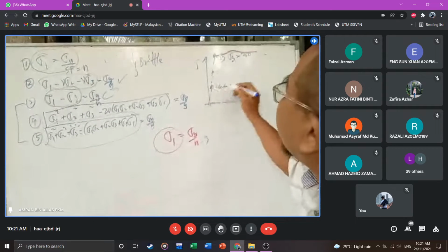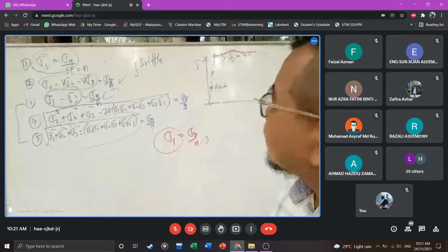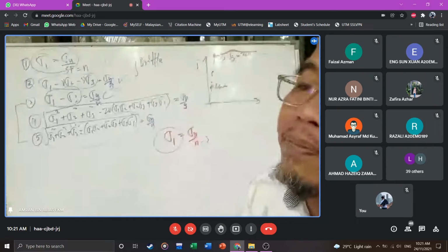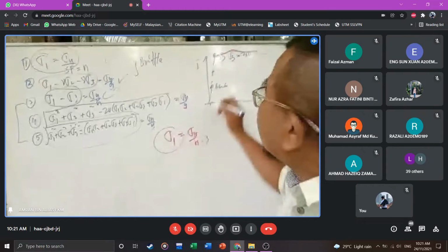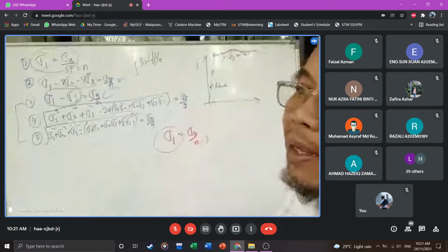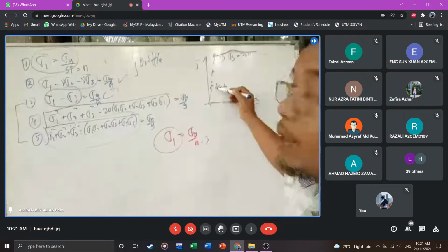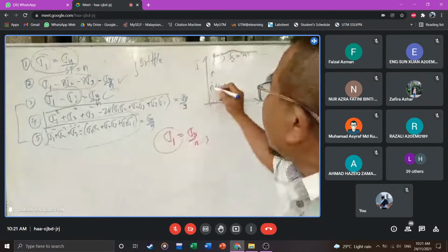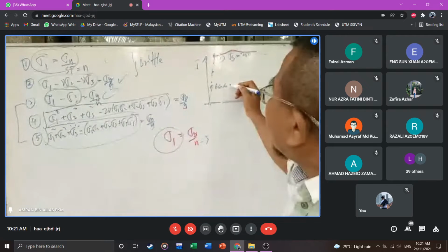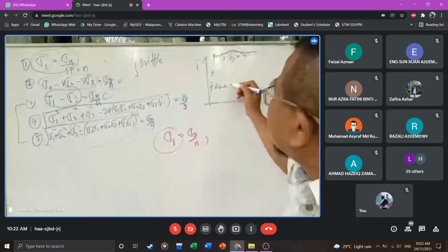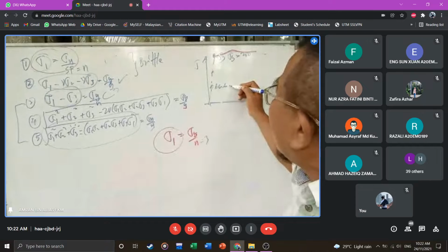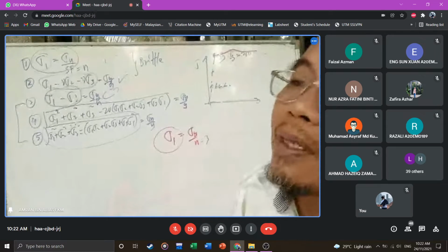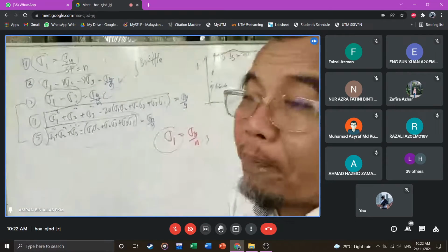That's the meaning of safety factor of 3, or 1/3 of the limit. We have the maximum stress happening there. This is the limit of the material. If the maximum stress is there, we have 3 times more. Double, triple. It's the minimum safety factor of 3.